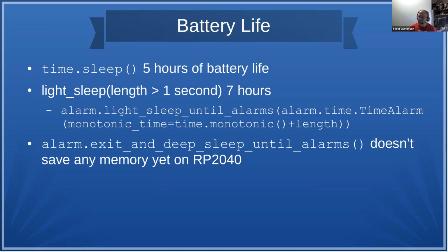The important part of this is that what you want to do is save the memory state of at least some part of your memory in a non-volatile state, so you know where you were, for example, in your state machine. So when you wake back up from sleep, you can resume exactly where you left off. Right now that's not implemented, but I know it's being worked on because I saw some GitHub issues logged against it.